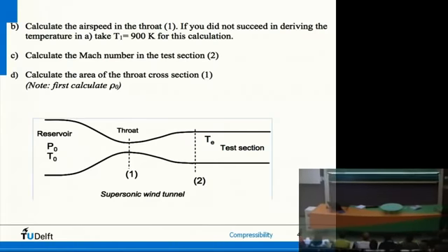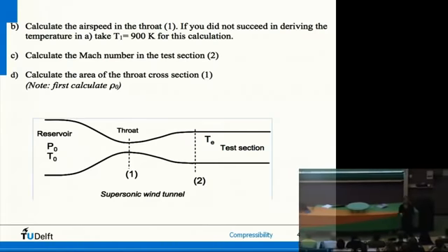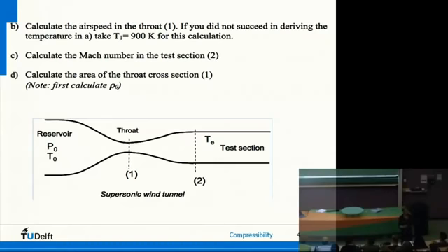It's going through the throat, the converging nozzle, diverging in a test section here. Now, the conditions are such that you get really to supersonic flows, and it was said it is a supersonic wind tunnel, if the conditions are such, and that depends among others on this contraction ratio, but also on the pressure behind this. Please note that the pressure in the reservoir was 9 atmospheres, so it's really pushed out. If it's supersonic, then at the smallest cross-section, which is called the throat, we will have the Mach number being equal to 1. And the Mach number is speed divided by the speed of sound. So here, the flow will exactly have the speed of sound. And that has to do with something we will explain to you next year, compressible aerodynamics.